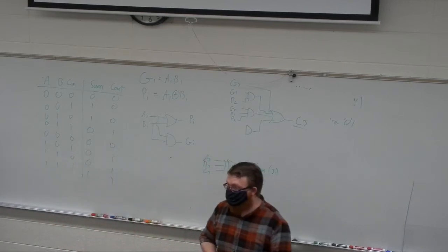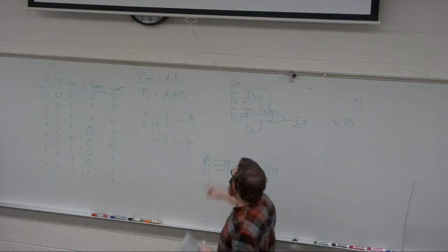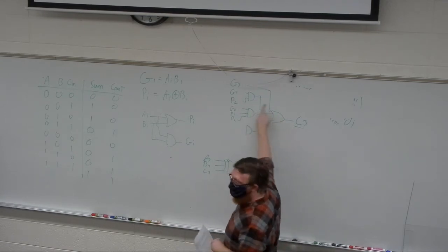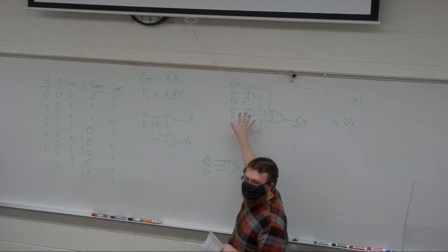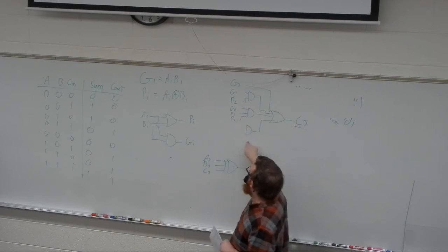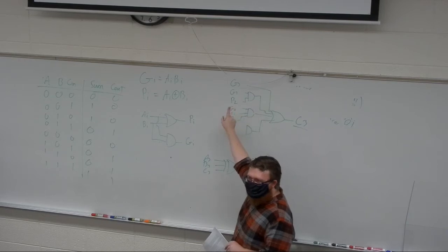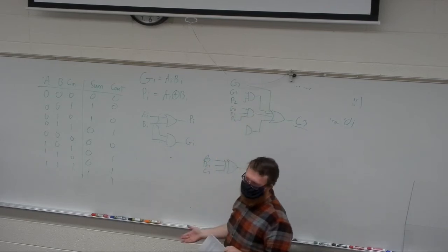The trade-off being that this circuit gets big very quickly, because this is the gate for just 3 inputs. And every time I add a sum bit, I add another AND gate, and each of the cascaded AND gates get 1 more input, which makes them bigger, right, by 2 transistors.